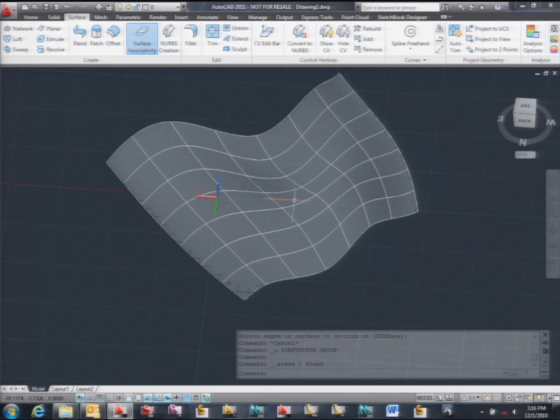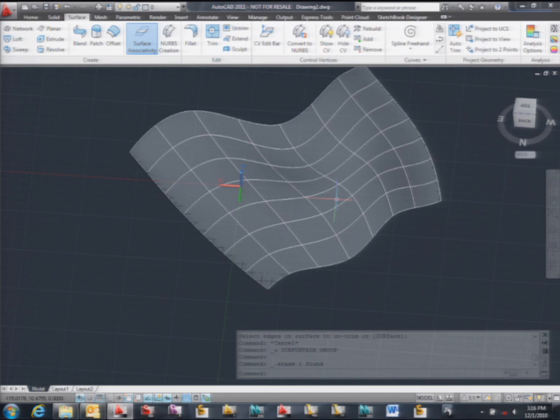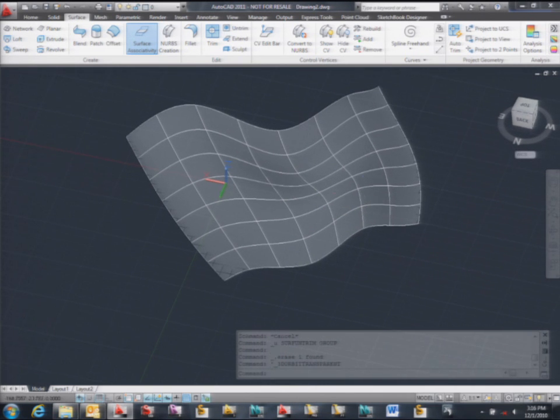It's tricky, but it's a good thing to know. I mean, if you get a solid model which is kind of big, if you do a VREP and remove everything, probably your solid model is 5, 6, 10 times smaller after that. So again, you need to know if you want to keep or not the history. In this case, it's always reevaluating, so it may get a little bigger, but it's not that you have 20 surfaces there, right? It's doing everything on the fly.